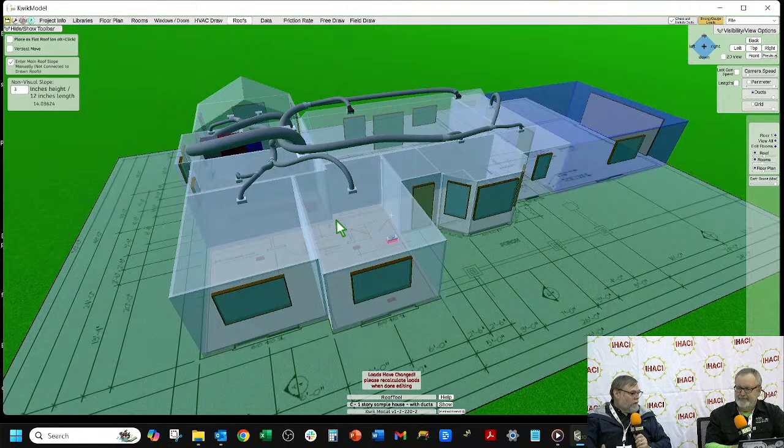We're in California. Do we need heat strips in most of the houses here in California? In 95% of the houses, I would say no. You don't need a heat strip in California. I'm trying to put together an article for the Indoor Comfort News about heat strips and whether we need them or not, because we use 120 volt air handlers. And so we save $1 or $2. We don't have to run electrical to it, the whole 9 yards. We just switch out to a heat pump.